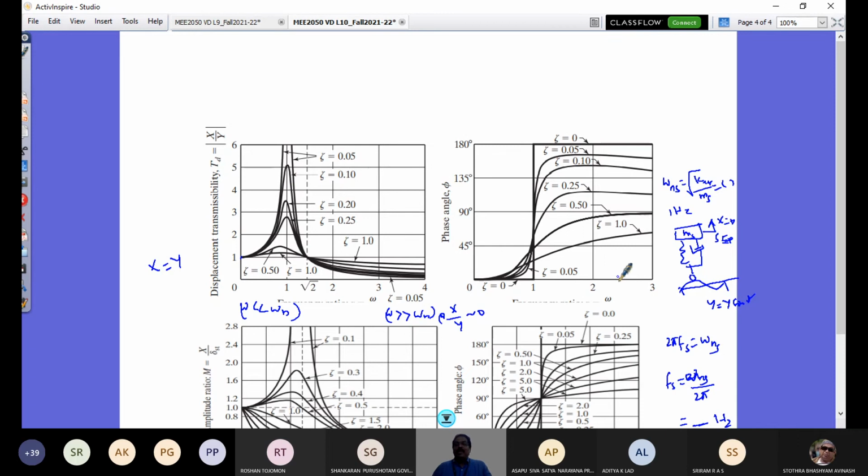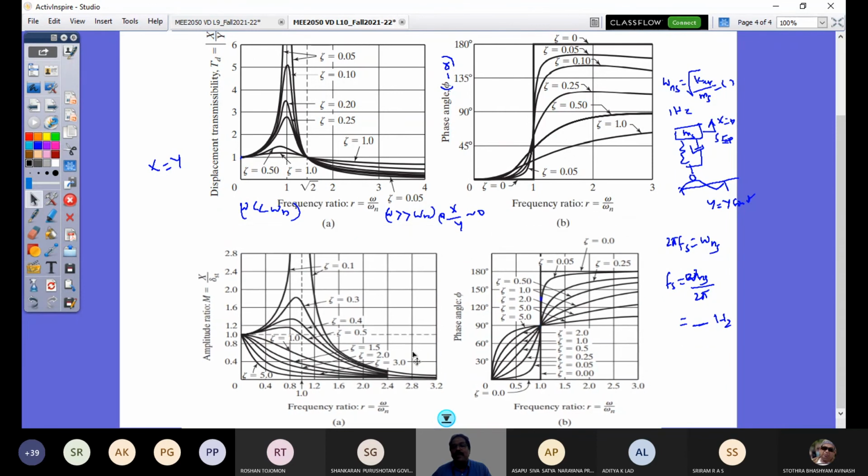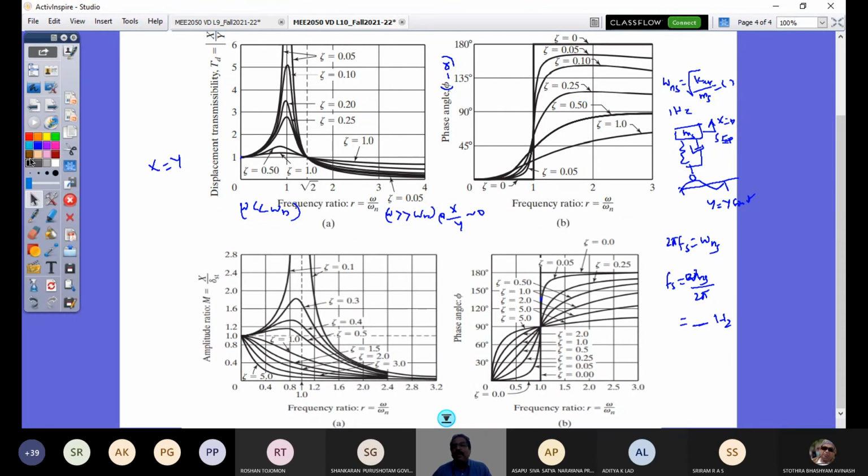And then you see on the other side, irrespective of the damping, at resonance we have seen that your phase angle is 90 degrees, but now it is no more the case because it's not phi. Please do correct it in the textbook. This phi is different, and I was retaining the same phi; this is phi minus alpha. So what is plotted here is phi minus alpha, and its variation with the frequency ratio. And see this difference: it is not a 90-degree phase difference at resonance.